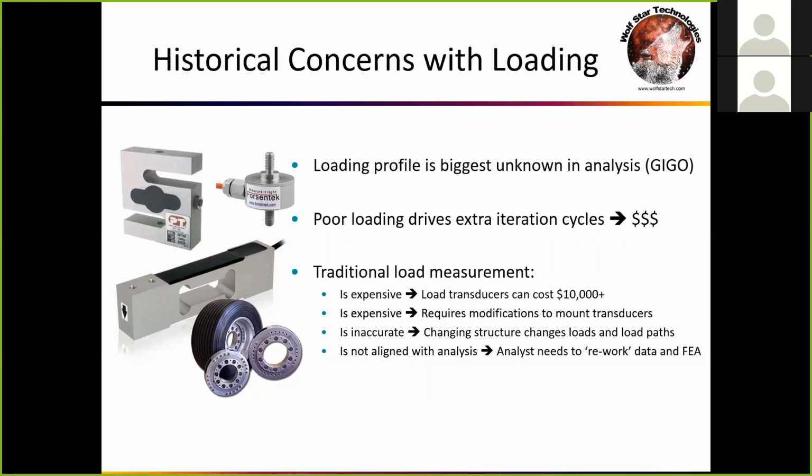And what people traditionally try to do is go out and buy load transducers, and install these load transducers in their structures and try to measure the loads. The load transducers can be expensive. They add mass. They change the load paths. You've got to change the structure. So you're measuring something, whether it's the right thing or not, you don't know. And then worse yet, when you want to work with the analysis community to use those loads, the analysts are working on the as-designed part and not the as-tested part. So typically, the analysts will have to rework the FEA model to make it look like the tested part so they can use the loads you're giving them. So this just isn't an optimal situation. This is just what people have got to deal with in traditional load measurement.